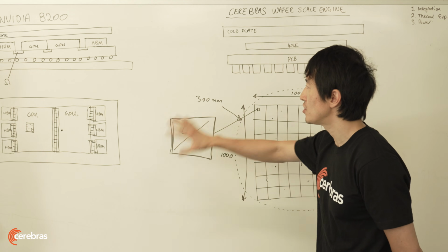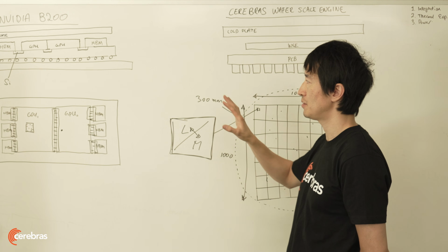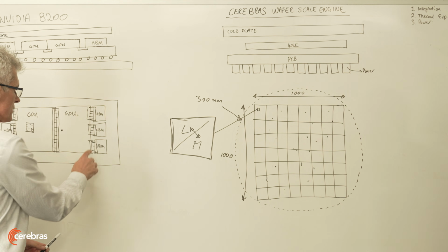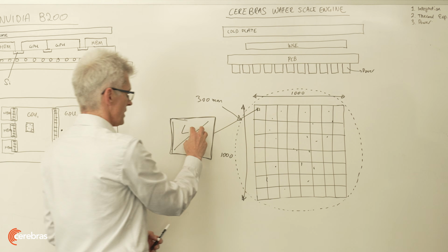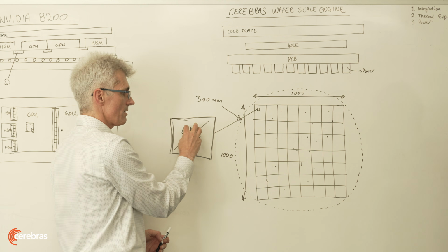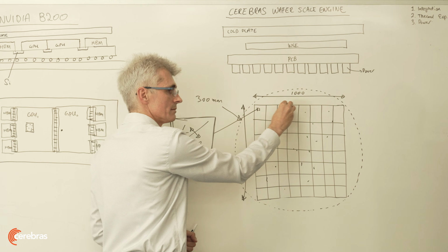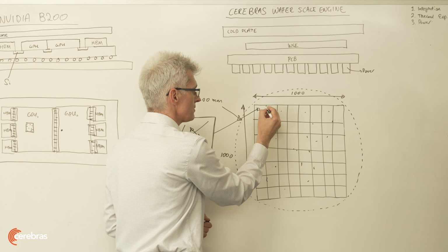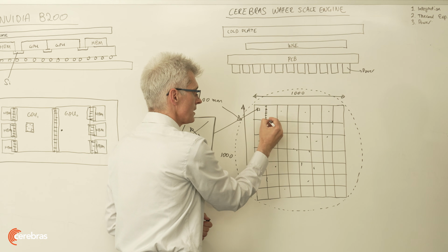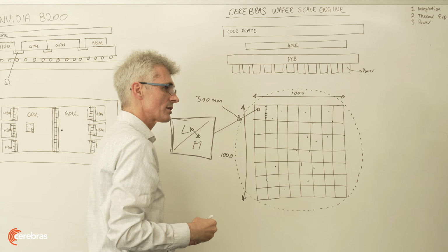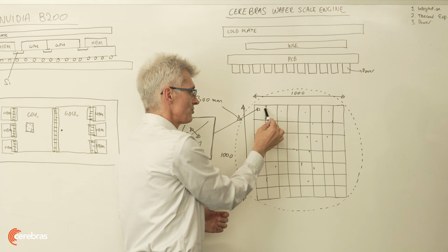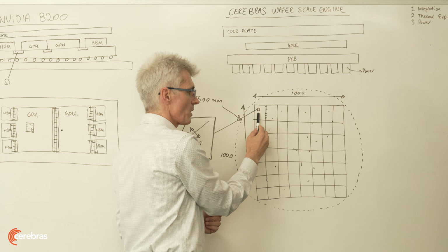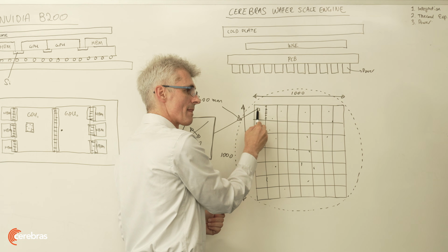So how does this architecture avoid some of the complexities and pitfalls with the packaging problems? First, connectivity. Because you have these small cores, you can have many of them interconnected very closely on one reticle, but also across reticles. And the lithographic process that you use to manufacture the wires across is the same process that's used for wires within a given die.